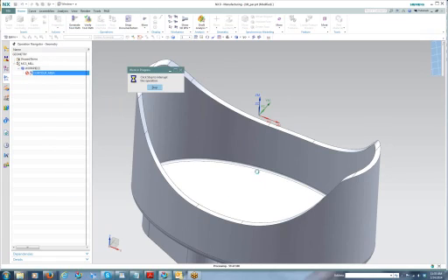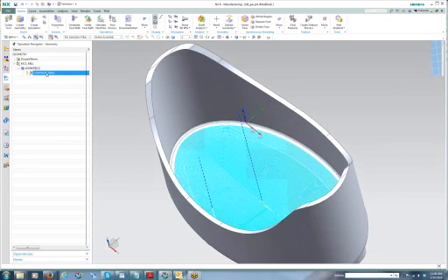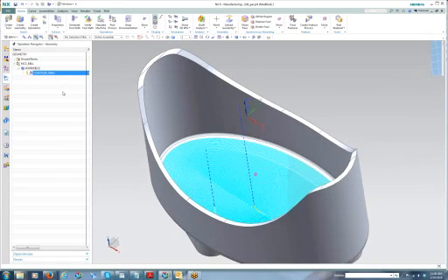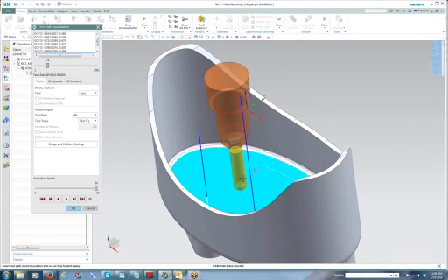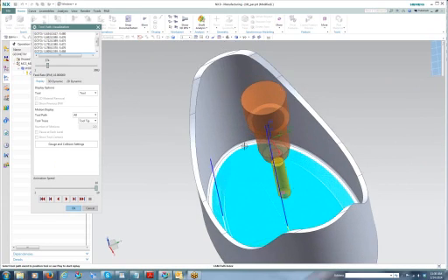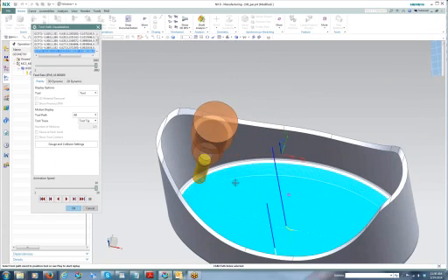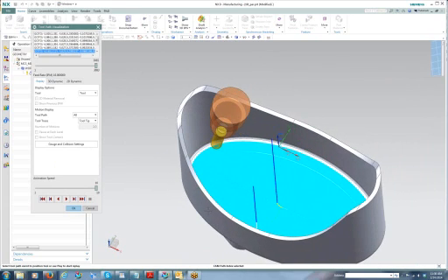And it thinks about this for a few seconds as it looks at every motion in reference to the wall geometry and tips only the areas that need additional clearance. Okay, here's our result. And it doesn't look any different here in terms of the center line of the toolpath, but if we go into the operation and verify, here in the middle where there are no clearance issues, the tool axis is still vertical, just as it was before. But watch what happens when we get to the outside. Here, where it's necessary, the tool is now tilted to provide for clearance.